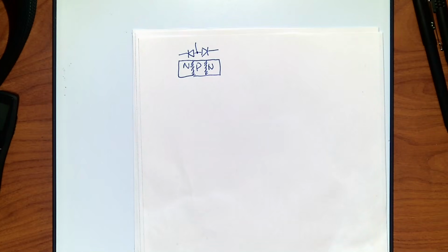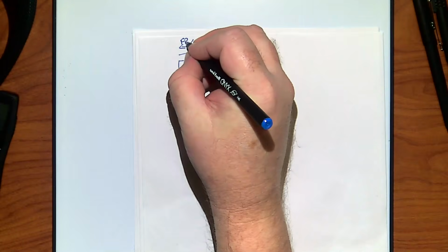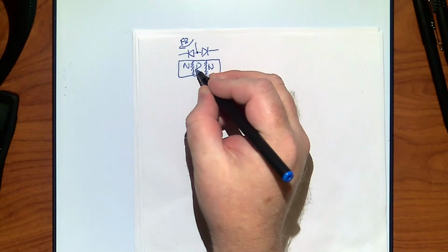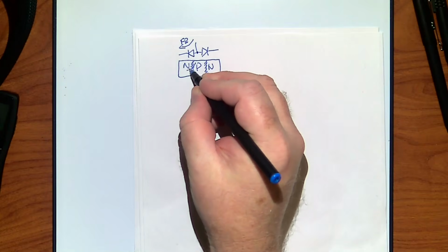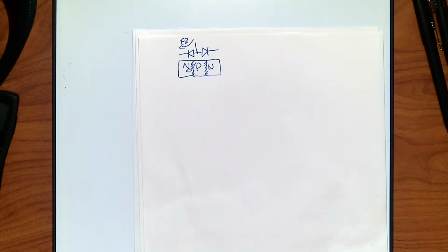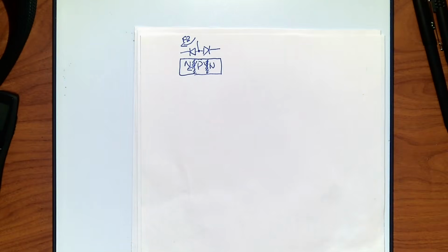To one side will start flowing. Yeah, see, this is the thing. Remember that these depletion zones are where there's not enough carriers. So what if I just took one of these and I forward biased it? So I put a forward bias on this. So now this depletion zone goes away. So it's now flowing. That means there's more than enough charge carriers to remove the depletion zone on this side, which means some of them come over here and remove this depletion zone also, because those charges are going to spread.